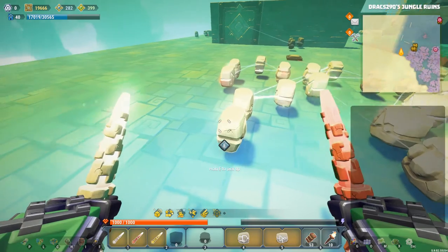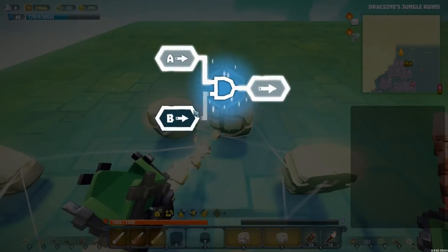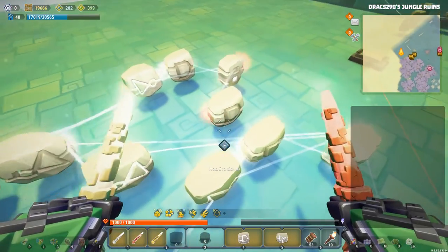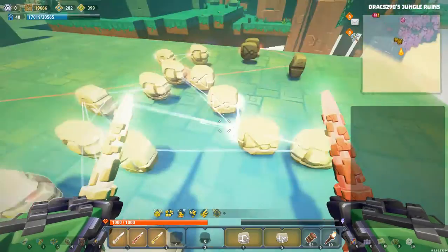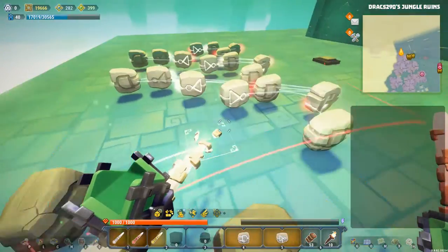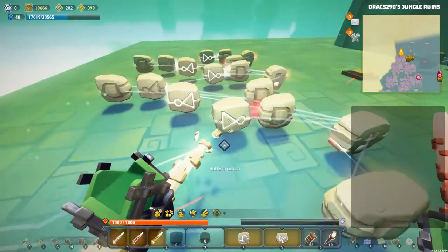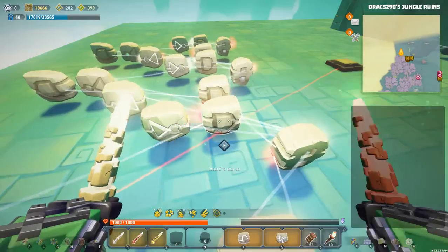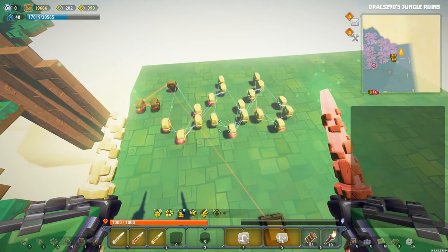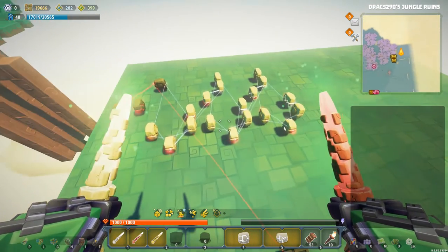Now we're going to take the AND gate and run that into the AND gates in the third latch system. So here we go, into the B side there, and into the B side over here. Perfect. Now all that's left is to run the output into this guy, so we're going to run the output from here up into the B side there, and the B side over there. So now this is a fully working latch system. So counter system, that's what I was trying to say there. So this is a fully working counter system that we've now gone through and built.